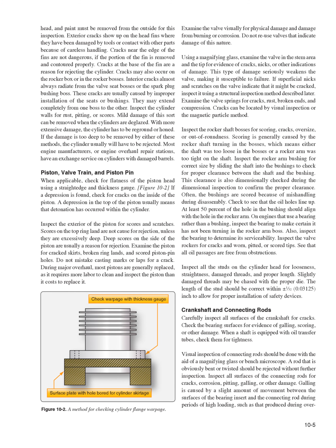Cracks near the edge of the fins are not dangerous if the portion of the fin is removed and contoured properly. Cracks at the base of the fin are a reason for rejecting the cylinder.